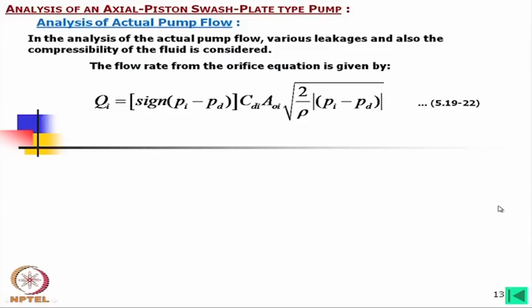So, when that particular orifice opens, whether it is maximum 1 centimeter square or 5 centimeter square, the coefficient of discharge is the same. When in one case it is half centimeter square, in other case 2.5 centimeter square, then also CD is the same. And it is also found that this CD remains more or less constant from the minimum opening to maximum opening. So, for a particular type of orifice these are fixed.